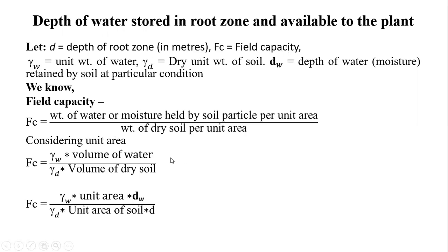Then we also saw that though we are talking about the whole water from field capacity being available to the plant, it doesn't happen so. The upper limit of the available moisture content is the field capacity, but when the water content in the soil goes on reducing, because of evaporation and uptake of moisture by the root zones, the amount at field capacity keeps reducing, and further reduction results in more pressure being needed to extract the water from the soil.